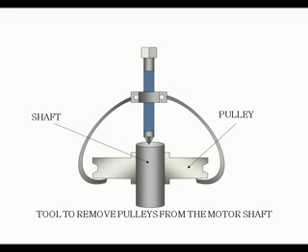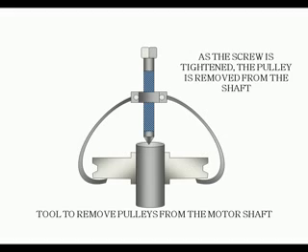To remove a drive assembly off of a direct drive motor or a pulley, you have to remove it from the motor shaft. It has to be done carefully so as not to damage the shaft. Special pulley pullers can be used, and set screws are tightened to the motor shaft that must be removed. These set screws are made of hardened steel. The end of the motor shaft should never be hammered in order to keep the shaft perfectly round.